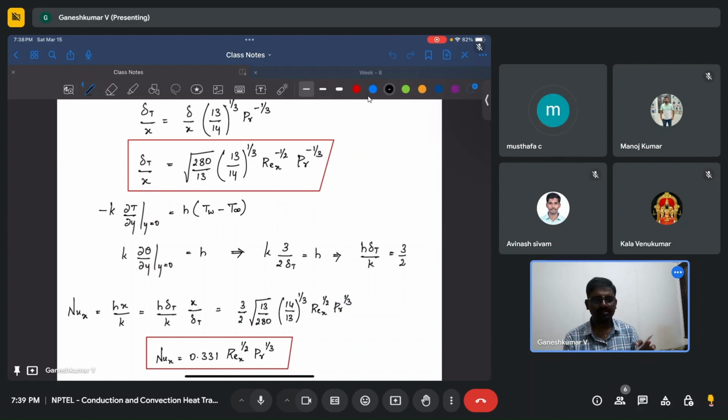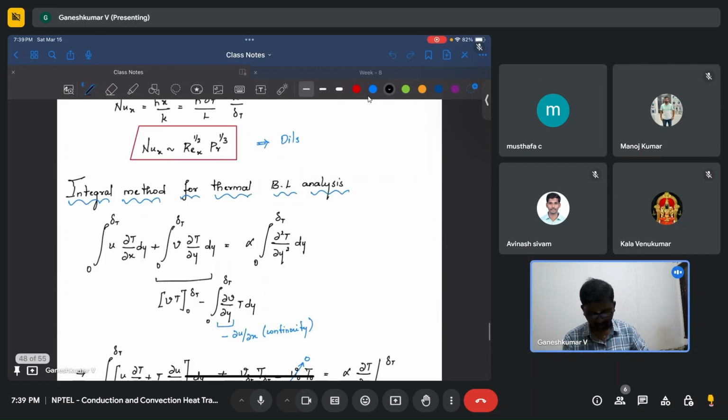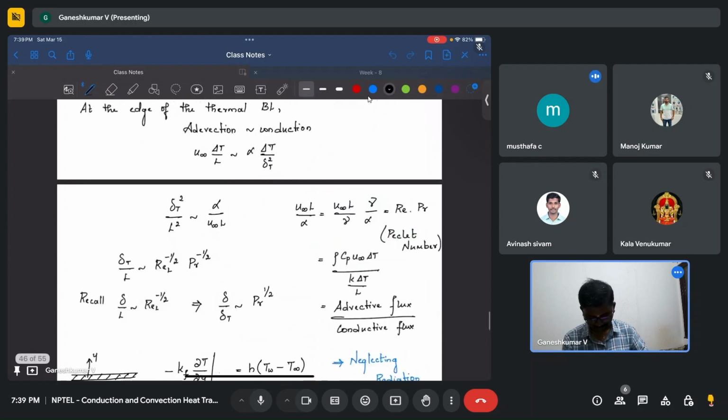I would not directly associate dP by dt to flow work. Only P times divergence of V is the exact flow work. dP by dt is just the manifestation coming because we express the energy equation in terms of enthalpy. So if you see the derivation, I would not call dP by dt flow work. That's what I'm trying to say.